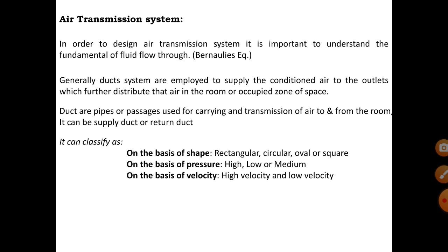See, through the duct there is a flow of air that could be hardly 12, 14 or 15 degrees Celsius. But the air outside the duct would be at the surrounding ambient temperature, that could be 30, 35. If I'm talking about hot humid weather, let me say the temperature is 35 degrees Celsius, and the humidity, let me take it as humid climate, would be around 65-70%. So let me say 35 degrees Celsius DBT and 70% RH.